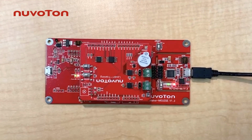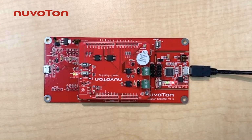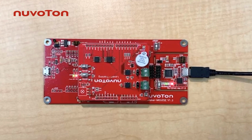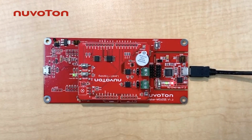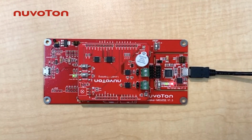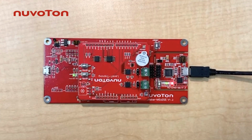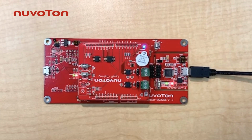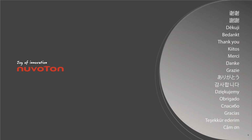At the same time, you will also see that the blue LED light toggles once per second in periodic mode, and the red LED light corresponding to the output pin PB14 toggles every 0.5 seconds. This is an example application of our timer function with LED light. Above is the introduction and demo of Level 1 training timer sample code.